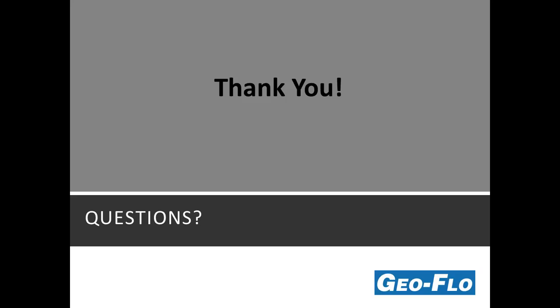a pump or pumps per heat pump, or we could still use the central variable speed pump with zone valves. So it's an advantage even with a single speed unit, simply because we have the ability to change flow based upon how many heat pumps are calling. So let's say we have 3 single speed heat pumps.